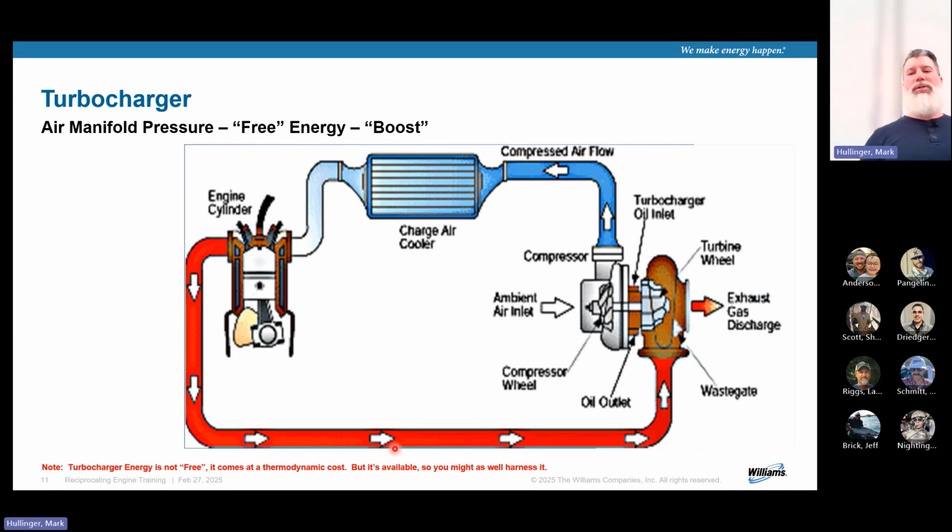Okay. Here's what a turbocharger does. You guys have seen pictures like this. So it's just a loop, goes around in a circle. Here's the hot side. Here's the cold side. So combustion or hot air, exhaust, excuse me, comes through here, spins this wheel right there. In turn, this spins that, compresses the air.